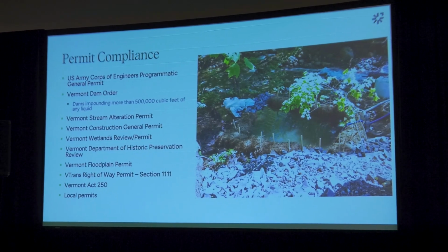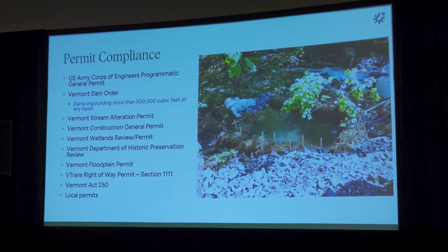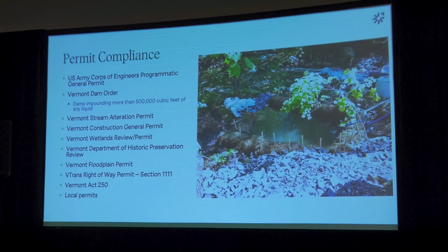So, permit compliance. You heard about getting the permits in the first place, and this is a long list, and not all of these permits would be required for every single project, but I think they need to be evaluated. Like Act 250, it's a big deal, and it's not necessarily triggered by our project, but if the project is on a site that already has an Act 250 permit, then you need one. Or VTrans, you don't always need one unless there's a state highway.